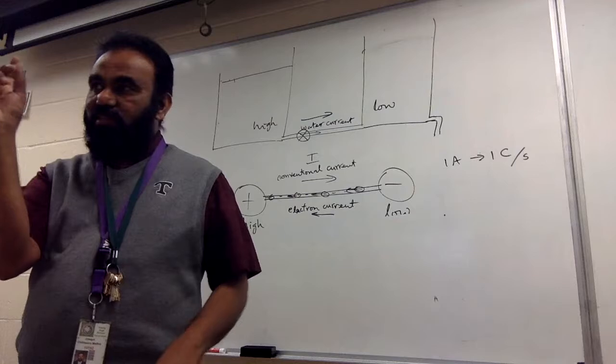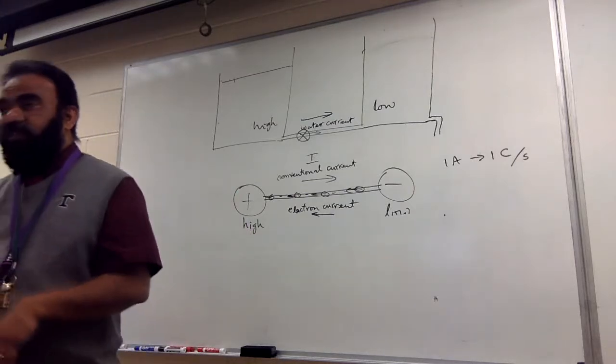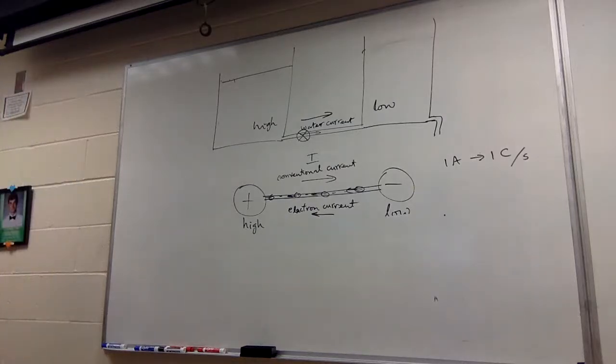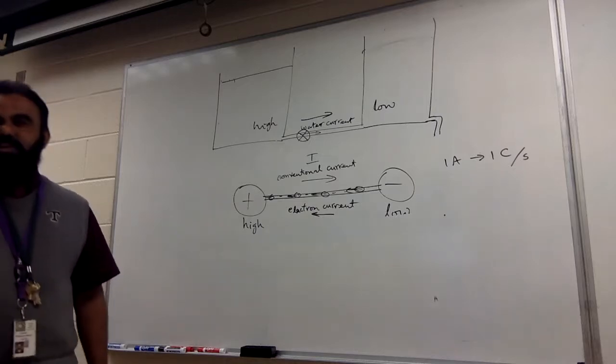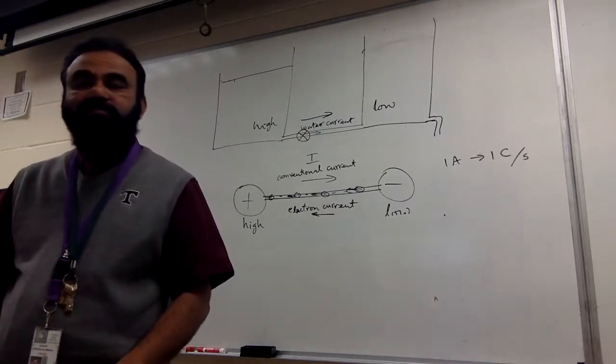There's a tester where you put the finger on top. Like, for example, if something is live, it's like a screwdriver. You touch the metal end to the place where you want to test, and you put your finger on top there. So the tester bulb will come on. Because it's a neon bulb, it will light up to let you know that it is live.